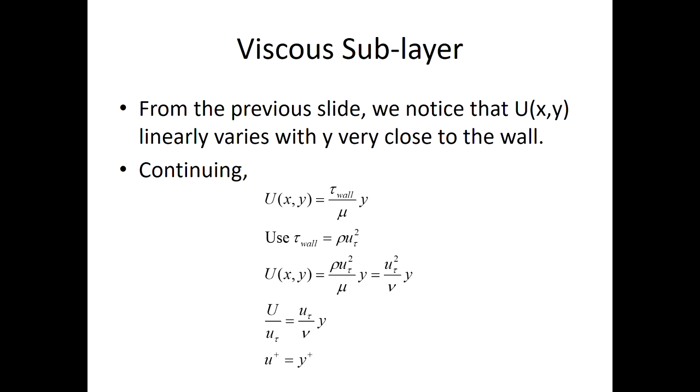Y non-dimensionalized by the friction velocity and the kinematic viscosity is called y plus. So you get a nice linear velocity profile in that regime. So this is the viscous sublayer that Prandtl hypothesized.